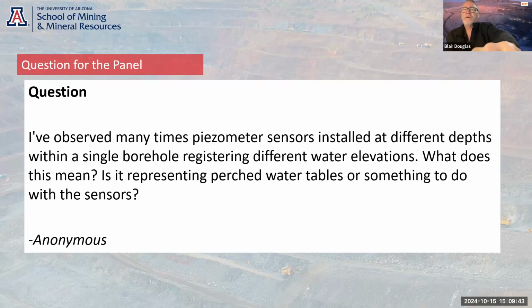One simple way to look at pore pressures in a profile is to look at the HU coefficient to give you some idea of whether it is vertically downward or upward. That is where you plot the depth of sensor from the surface against the pore pressure, and essentially a hydrostatic line runs through the middle of it. With that, you can see where each sensor sits in relation to hydrostatic.